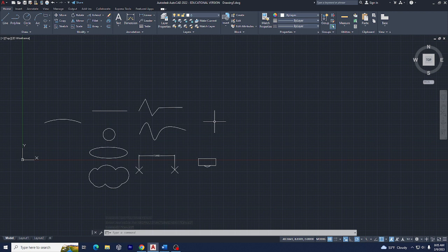So there are precedents that take place in this when you're working with grips and other things. So when you're working with it, let's look. The precedent order is object snaps come first, explicit coordinates second, ortho third, point filters fourth, grip auxiliary grid fifth, grips sixth, snap seventh, and digitizing a point location is eighth. So object snaps have priority over all other point selections made. As far as grips are concerned, ortho overrides grips. So ortho's 3, grips are 6. Well, 5 and 6. And then object snaps is 1.